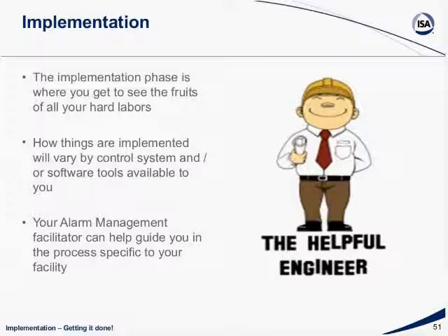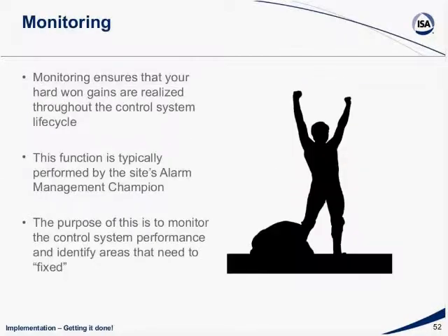Okay, we've done the rationalization, we've done MOC, we've done the implementation, and everybody is done except the alarm management champion. Because now, as part of the ISA standard, you need to monitor your system performance. And this is typically done on a monthly basis. It's really not that difficult because if you have the right tools available, they'll generate some very clear and simple reports that you can use to monitor this.